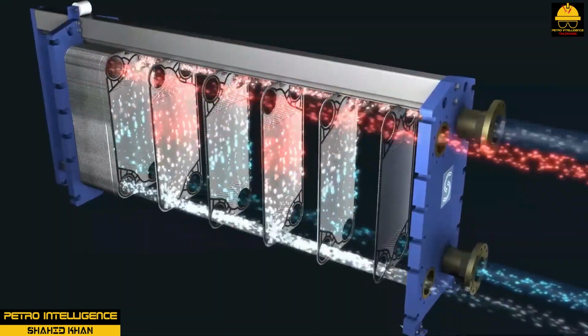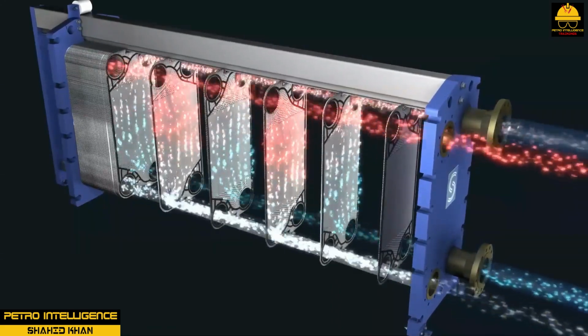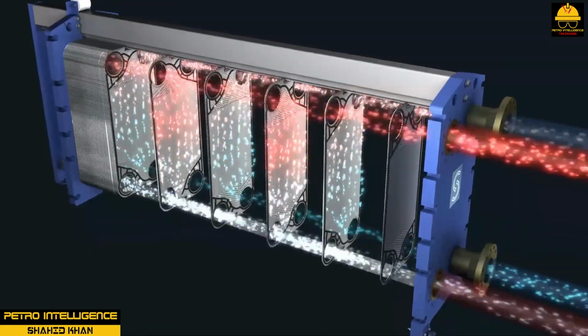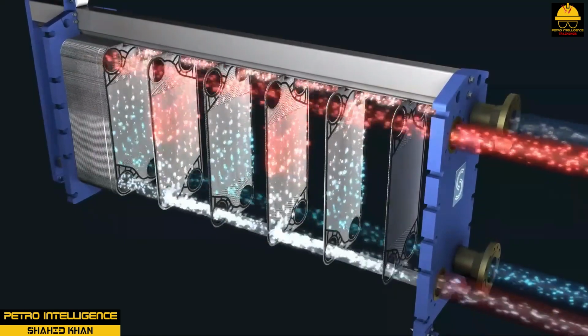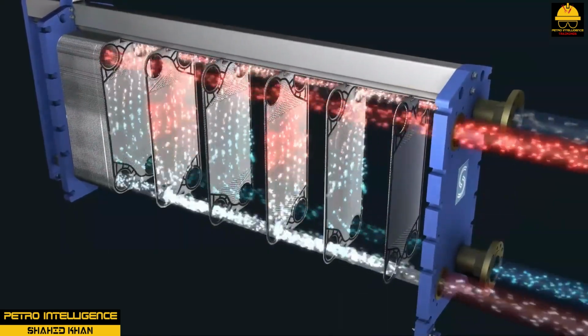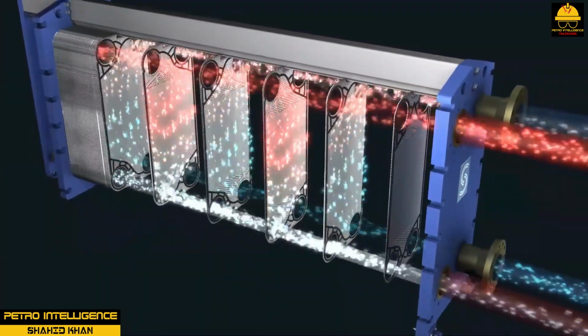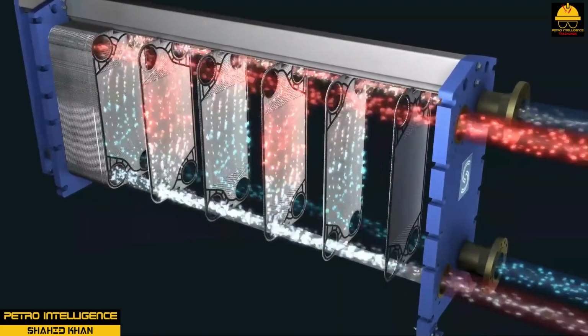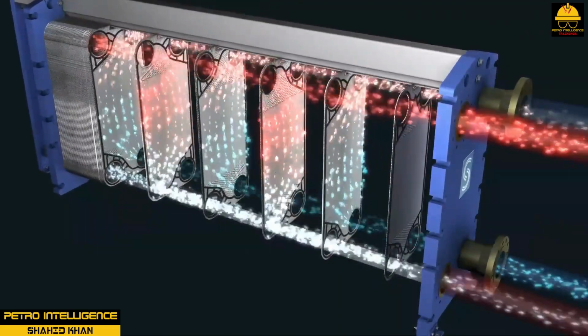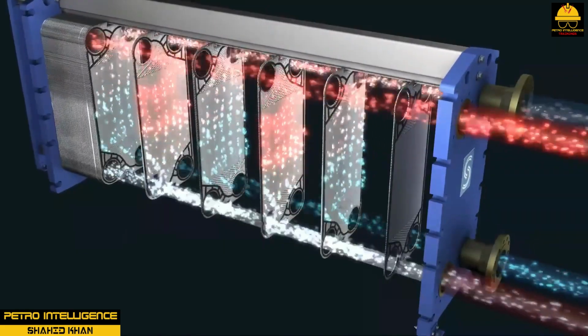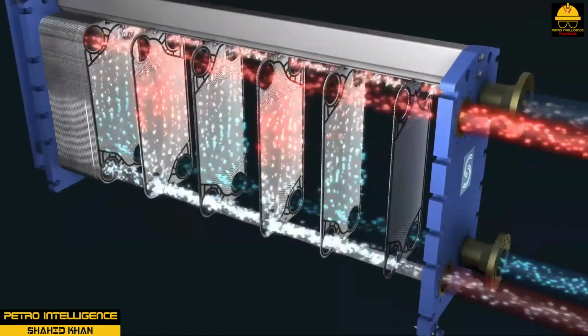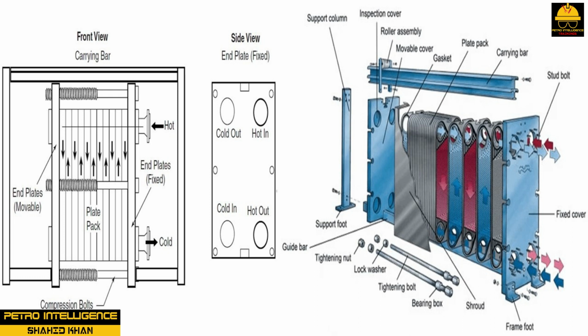Plate and frame heat exchangers have several advantages and disadvantages. They are easy to disassemble and clean and distribute heat evenly so there are no hot spots. Plates can easily be added or removed. Other advantages of plate and frame heat exchangers are their low fluid resistance time, low fouling, and high heat transfer coefficient. In addition, if gaskets leak, they leak to the outside, and gaskets are easy to replace. The plates prevent cross-contamination of products.